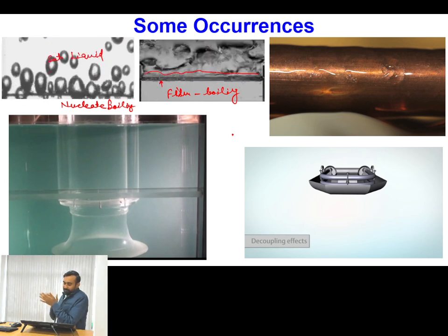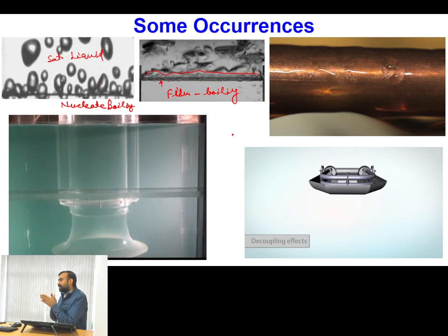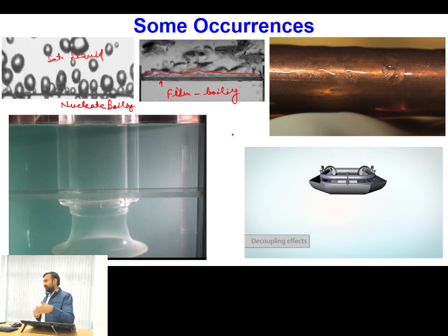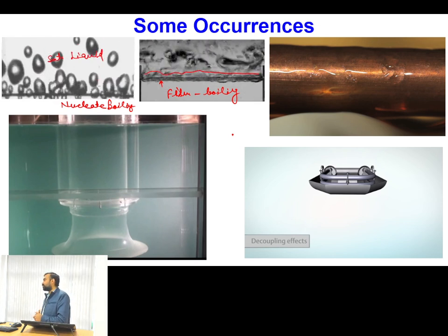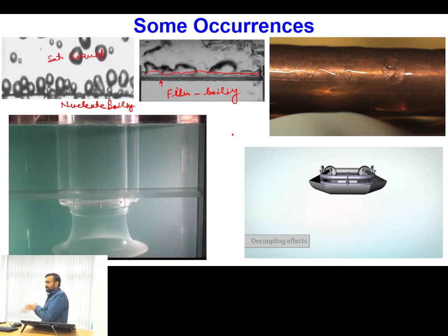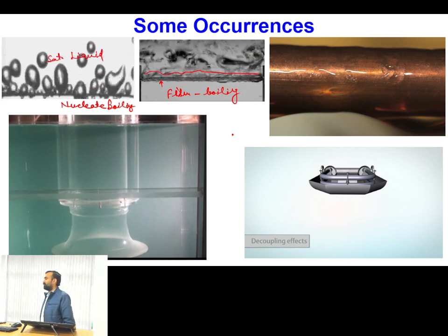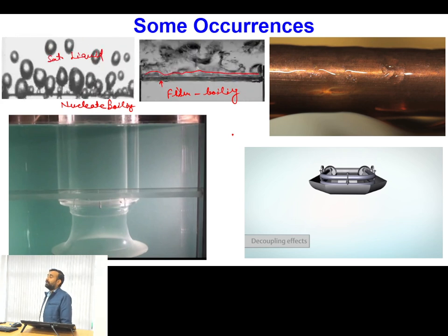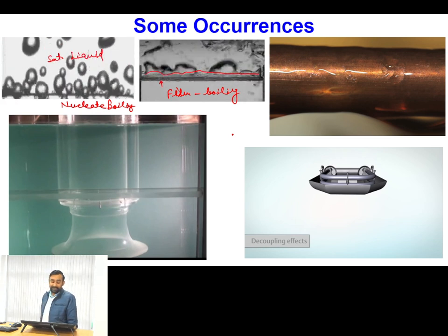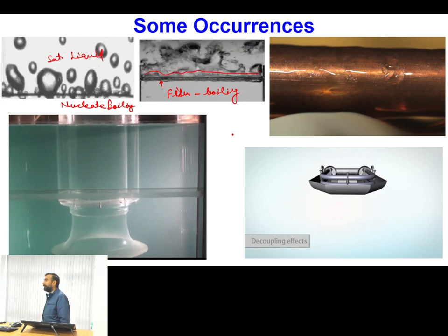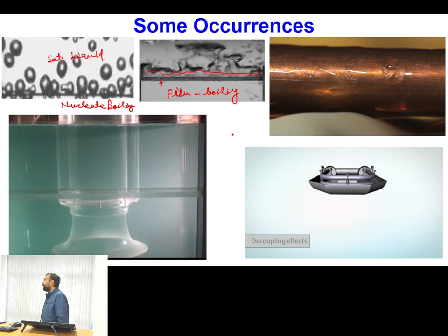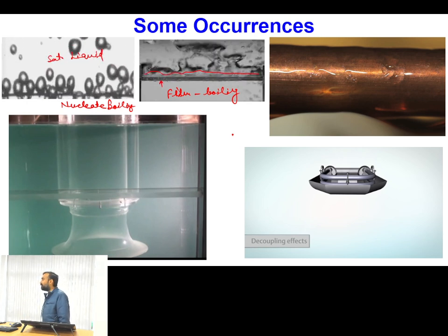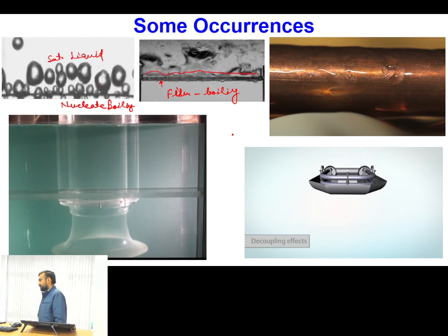Okay, so wherever gaseous contact comes with the surface, the rate at which that heated solid is receiving the heat from some heat source, it will not be able to dissipate at the same rate to the liquid, and there will be formation of hot spots, and these hot spots sometimes may be detrimental, and if their temperature increases excessively high, it can lead to failure in terms of fracture because of the pressurized liquid present in the system, or because of their melting also.